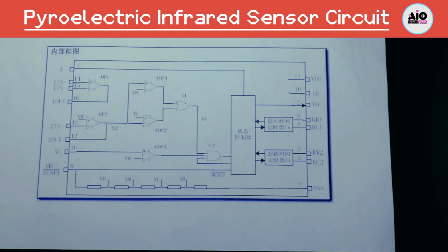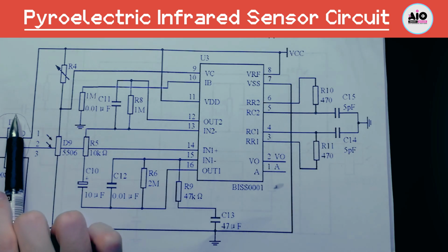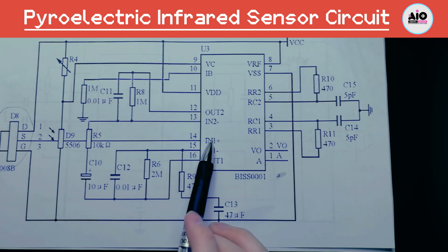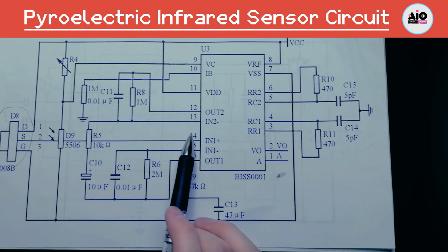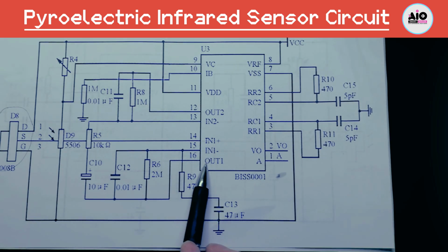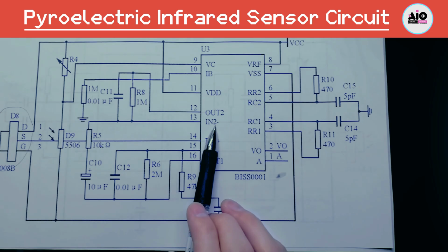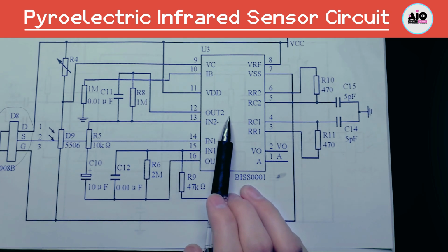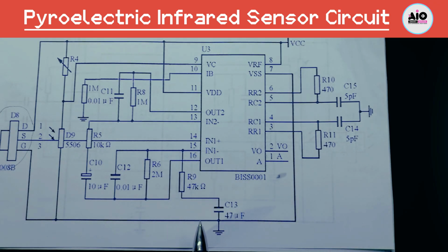So what is its internal working principle? We only do a simple understanding of it. Mainly, let's take a look at the working principle of its external circuit. In this circuit, the output of the thermal infrared sensor at the front is pin 2, so it passes through pins 14, 15, 16. These 3 pins are the first operational amplifier. After passing through the first operational amplifier, its signal output terminal, pin 16, passes through the resistor and capacitor and then enters the second operational amplifier for amplification.